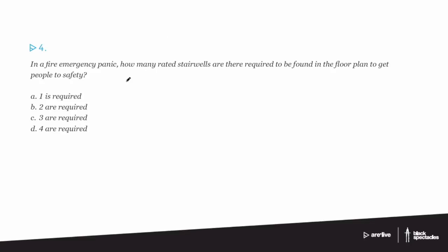So I can pretty much guarantee you, from generally knowing how these things go, that it's probably answer B and might possibly be answer C. If I was in a hurry, running out of time, I'd just answer B, because 2 stairs is totally standard. The only reason it would go more than that is if there were a lot of people, like an assembly space, or a really big square footage footprint, which when divided by the 100 square feet per person we found a few minutes ago would again be a big number of people, or if there were really long distances. But none of those seem likely. It all seems pretty compact, so it's probably B.